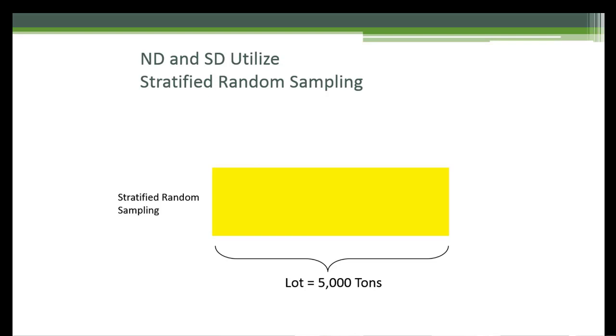The other thing is you generally like to have it spread out, so you can also use those samples for quality control, not just for acceptance. And so having them spread out over the entire day allows you to make, if you remember the terms, monitors and adjusts the process. That's what we're looking at.